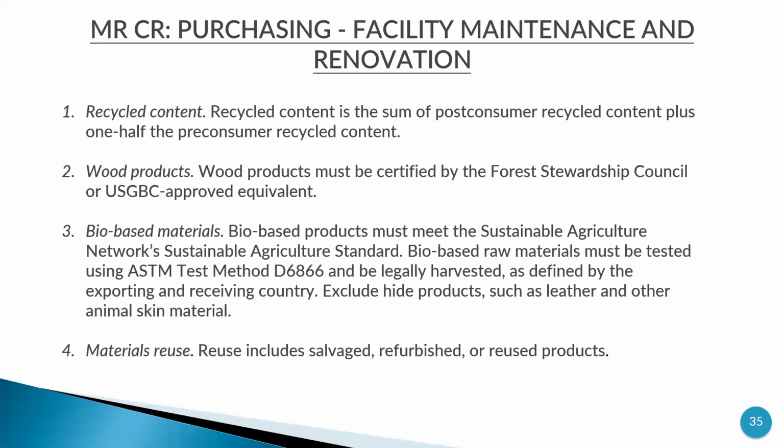When you say recycled content, it is the sum of post-consumer recycled content plus 1/2 of the pre-consumer recycled content. One full portion of post-consumer plus half of pre-consumer.